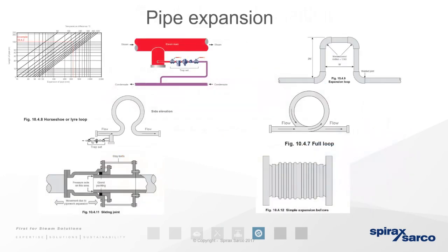Staying within the pipelines, we know that when you add heat and subtract heat, you are going to get pipe expansions. And while Spirax don't make expansion devices anymore, we can offer you guidance on how much expansion you can expect to see if we know a few key parameters, such as your temperature, surrounding temperature, your pipeline pressure, which relates to temperature again, your pipe size, as well as the length. We can easily work out what that expansion is within that system.